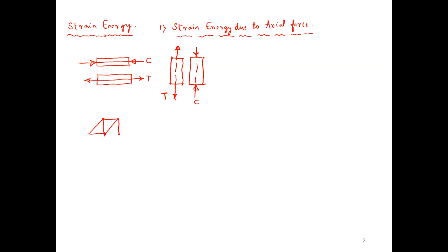Trusses. These are all pin jointed. Here you are having either tensile force or which kind of forces? Only forces we are getting. There is no moment. Compression, right? Nature of the force, compressive or tensile. Method of joints, method of sections. Example, trusses. So the only axial type of forces we can expect is in trusses.